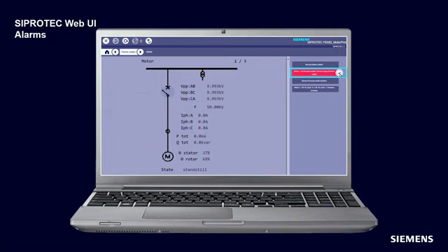First is that we can show the screen of the relay and additionally alarms, which we define in DIGSI 5, which we can acknowledge. Here, for example, I ran over the restart inhibit temperature, and now this alarm is red because this signal is active, motor switched off, you see. This remains red until the calculated temperature goes under the restart limit temperature, then this becomes green, and then I can acknowledge this signal, and then it becomes gray. So here is the possibility of having alarms which you can acknowledge.